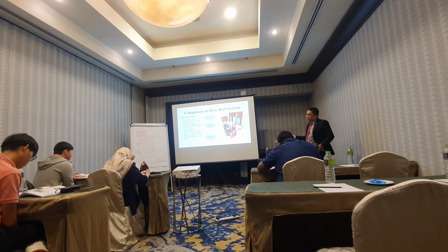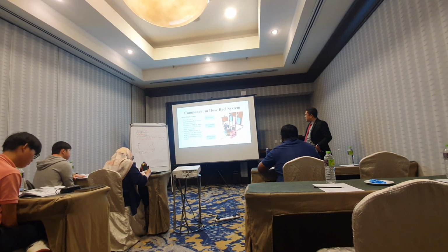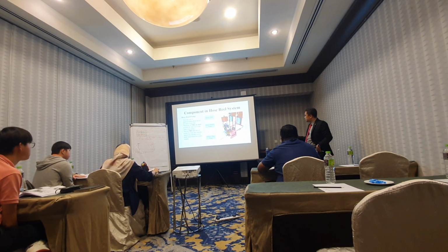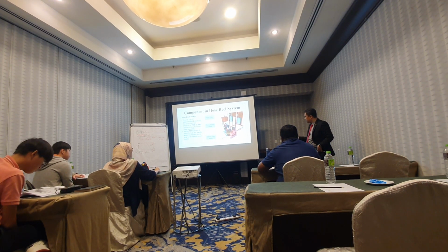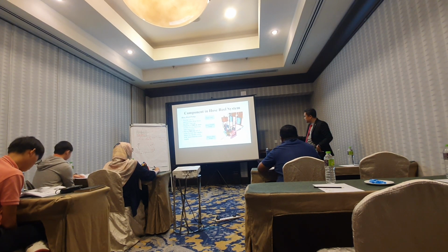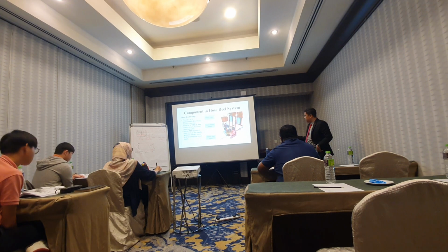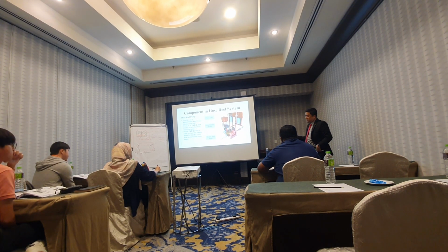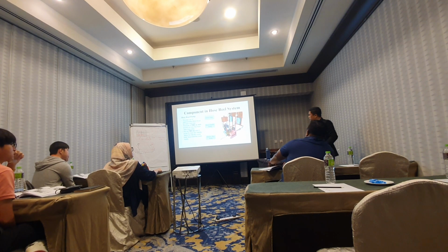In this picture you can see the diesel tank is separate, a smaller diesel tank. The diesel engine operating the pump must have a diesel tank capacity that ensures the pump works for an hour, not less than that.